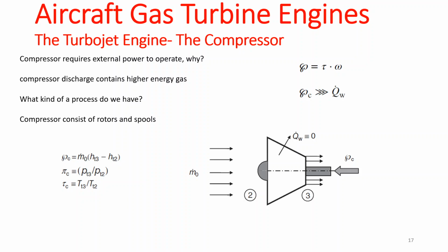The static pressure rises across the compressor blades and causes total pressure loss. Okay. Why does the static pressure rise? To answer whether a process is isentropic, you have to make sure whether it's adiabatic and reversible. Is this process reversible? No, because of the wall friction and all of those frictions that are happening. The frictions are always there, right? So it is an irreversible process.